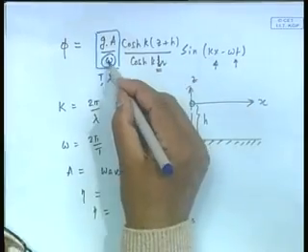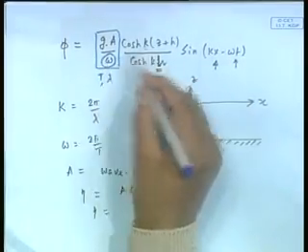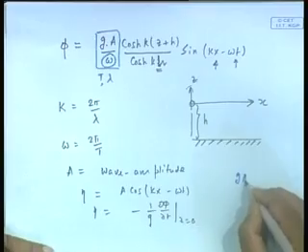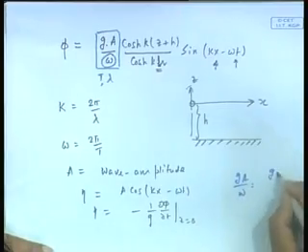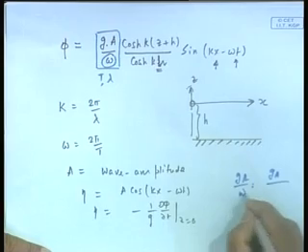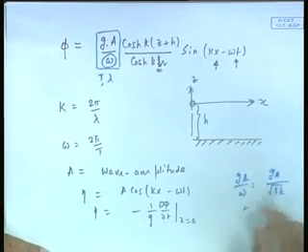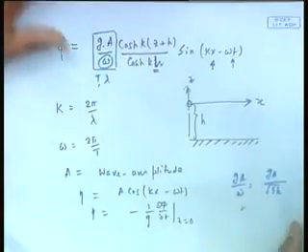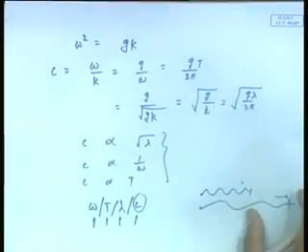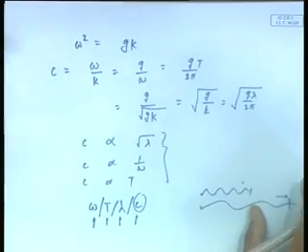It can be something like g a by root over gk. For example, in the deep water case, omega is root over gk, and I can relate that to root over g 2 pi by lambda, etc. So, this is only a question of convenience of how we proceed. It really depends on the way we want to look at it.